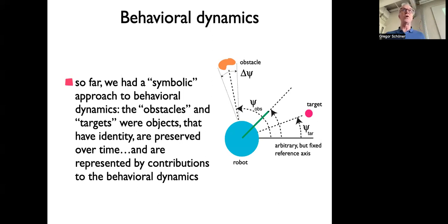And there's a whole process of matching which sensory input is an update to which of your Kalman filters, and when do you actually have enough evidence to start a new one. Maybe occasionally you will close down one, and so on. And there are other approaches to that. Computer vision, for instance, is a field that deals with creating instances like that. So that's a kind of complication that would arise.